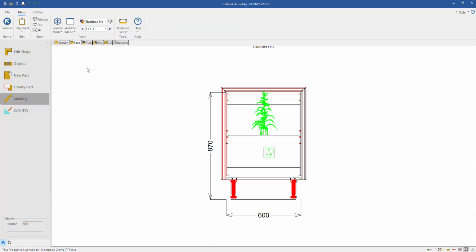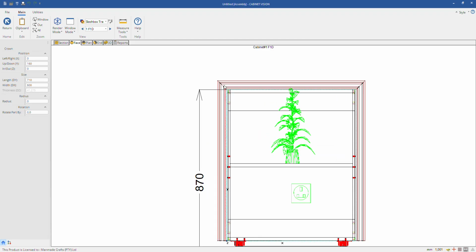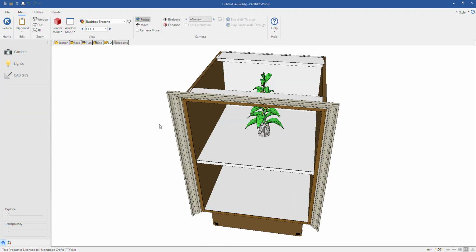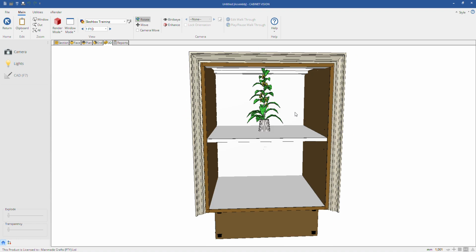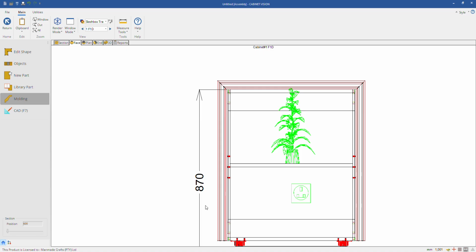I can now still go on face, in molding, in face view. Sorry, do you do the molding around the doors as well? You can do the molding wherever you want. Because you can now go and select this molding, and you can say in out 600, which is the depth of the unit, and you push it right against the back, or bring it right against the front. So you can use that to design moldings around your units or in between your units, or however you want to, or above the cabinets. There's a different way to do it. This is just in the unit specifically.